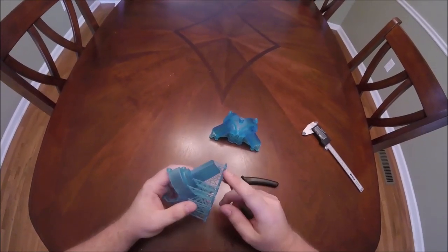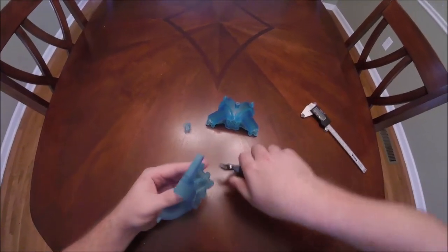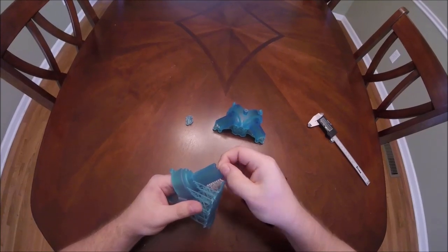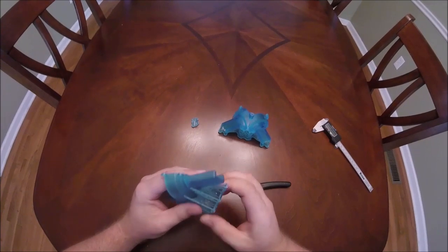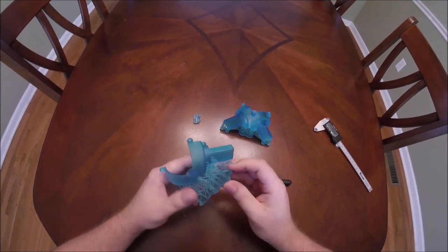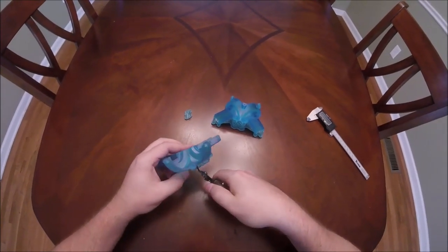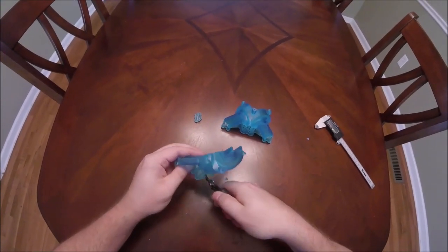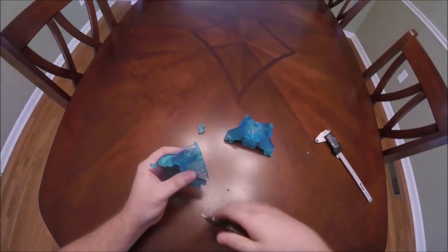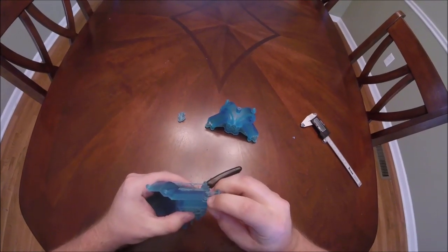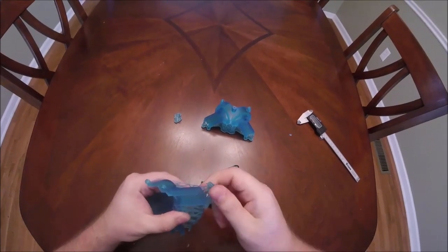So I'm going to start sort of at this end of the part, and I'm just going to clip the base so we can remove that part separately, and you can see the whole thing just fell off there, which is great. And there's just very little amount of mark left from the supports. So we're just going to go through the whole part with that sort of mentality and get all these supports off here. So I'm going to crack the base in a few places. And then I'm just going to start looking at how these supports are formed and just start sort of fatiguing a couple of these, breaking a couple of these out of the way.